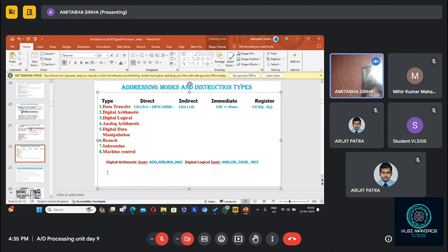Internally, another kind of thing, a software interrupt, is done by some watchdog timer. A watchdog timer is nothing but a register whose value will be decremented after execution of each instruction. You can set the value accordingly.